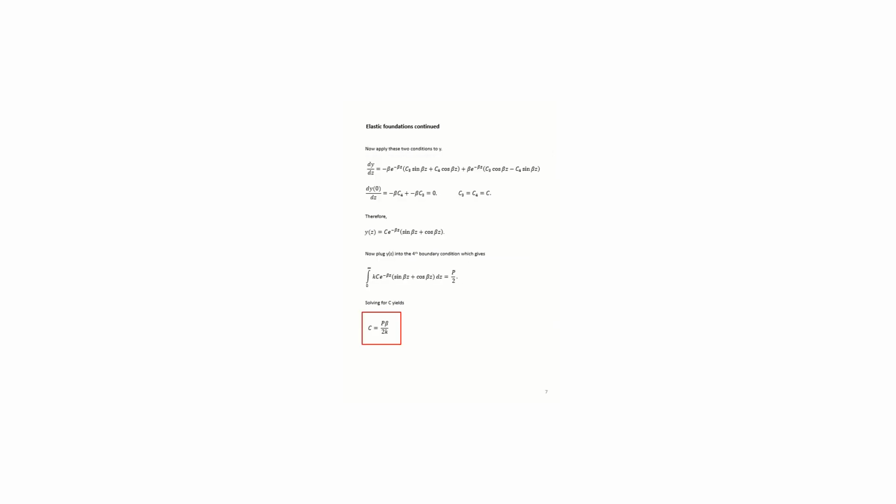So I'm integrating on the positive side, 0 to infinity, and I'm saying that the integral of that elastic foundation force is equal to half of the applied load. So the foundation on the positive z side here has to carry half of the load. And that's what we're saying with that equation there.